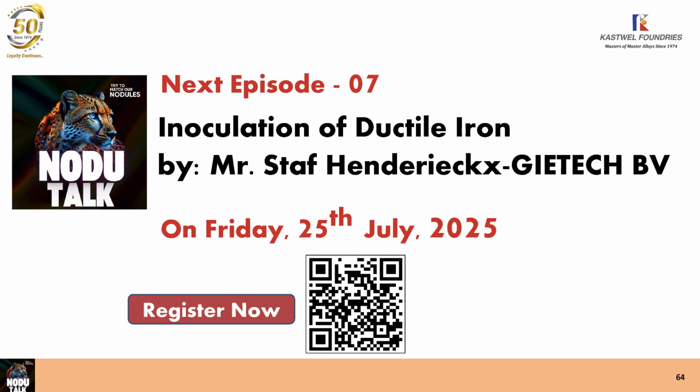And secondly, there are also the rules about the thickness, because you have two things. If the ratio is not okay, you can have a problem. And the longer a casting stays liquid, the more time your degenerating elements have to cause problems, or the more time your cerium, which cannot compensate for degenerating elements, has to destroy the nodules.